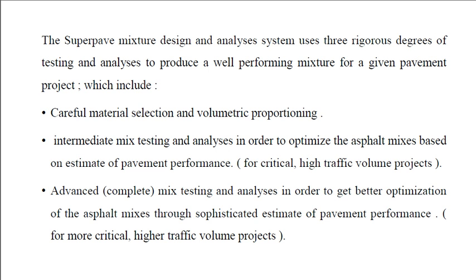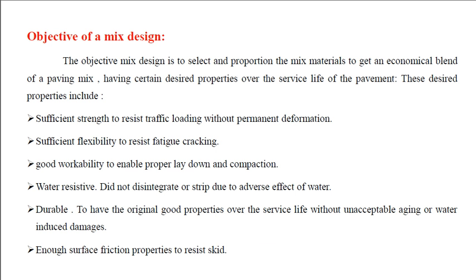Now, the objective of the mix design is to select and proportion the mixed materials to get an economical blend of paving mix having certain desired properties over the service life of the pavement. These desired properties include first, sufficient strength to resist the traffic loadings without permanent deformation. Second, sufficient flexibility to resist fatigue cracking.